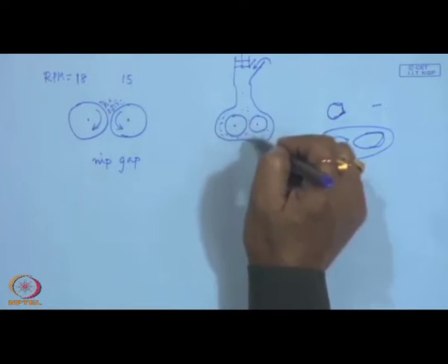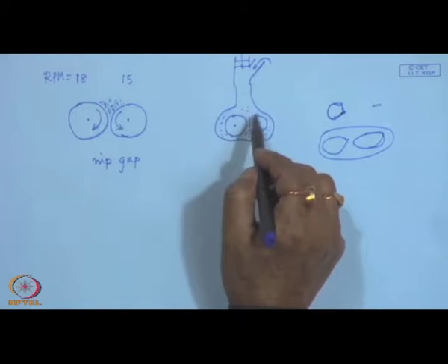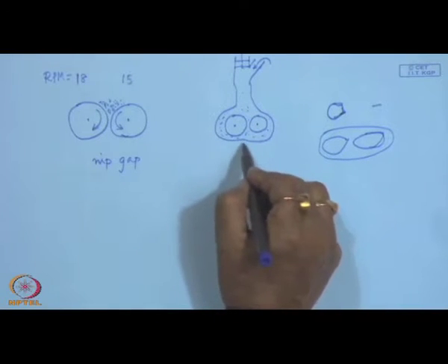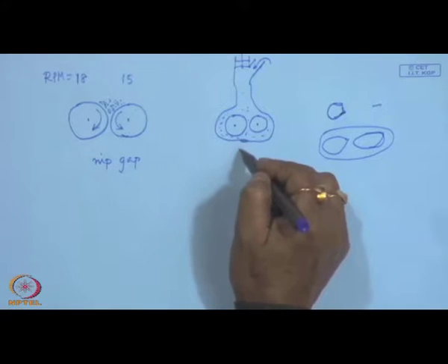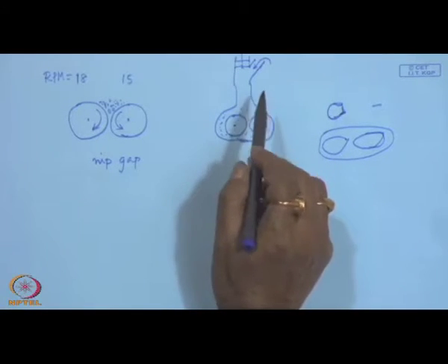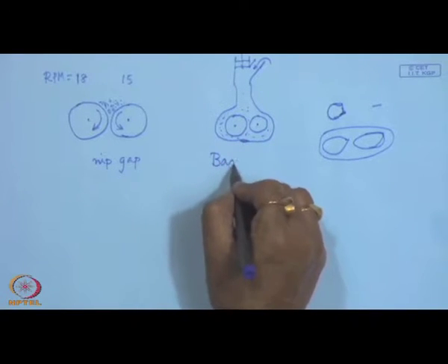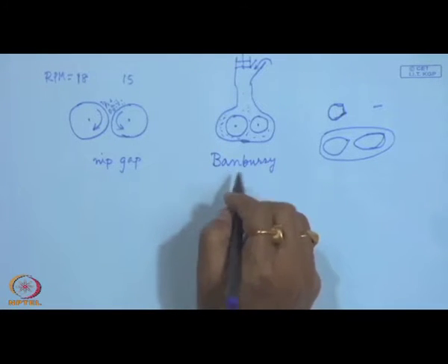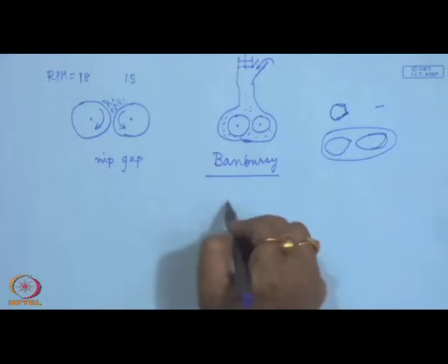So, this way we have a facility of polymer mixing in a closed chamber, and there can be a dumping door at the bottom. After mixing, the mixed product can be dumped down from here. That is known as an internal mixer. There are various types of internal mixer, say Banbury mixer, or there can be many other names. So, internal mixers or kinetic mixers.